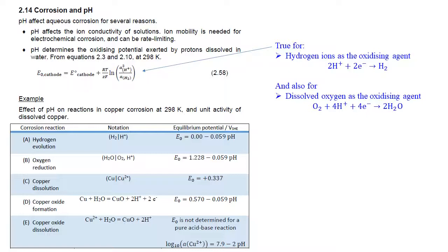Taken together, if we can answer both of those questions, suppose we find out that both the metal and its oxide do tend to dissolve, then we learn that the stable phase is the dissolved ions, in which case we predict the metal is going to dissolve. It will corrode actively, meaning continuously, regardless of whether it has some surface oxide. On the other hand, if for those two questions we found the metal dissolves but the oxide does not, then maybe the metal might be passive against corrosion.